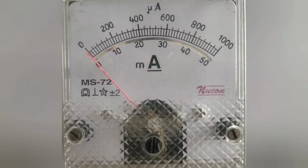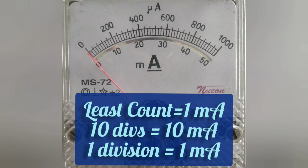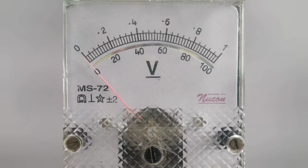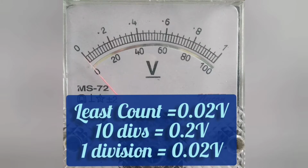Now let's find out the least count. Now students, you can check 10 divisions is equivalent to 10 milliampere. So one small division is equal to 1 milliampere. So the least count of this milliammeter is 1 milliampere. Again, for forward characteristics, we will make use of a voltmeter of range 0 to 1 volt. Now here students, from 0 to 0.2, there are 10 equal divisions. So one minimum division will have a reading of 0.02 volt, which will be the least count of this voltmeter.